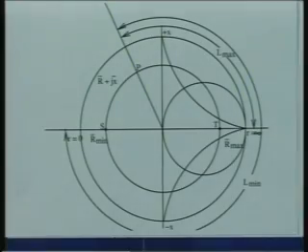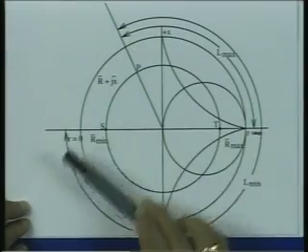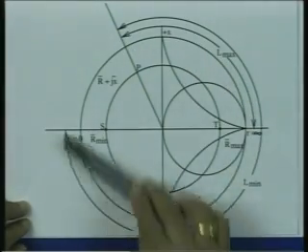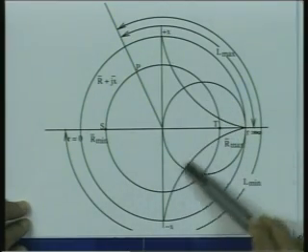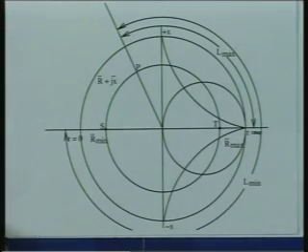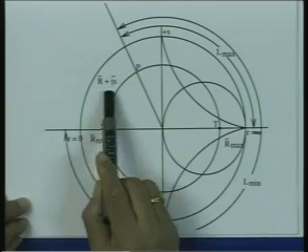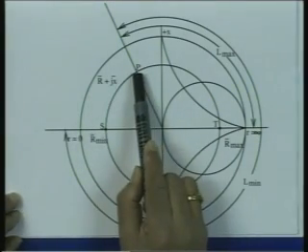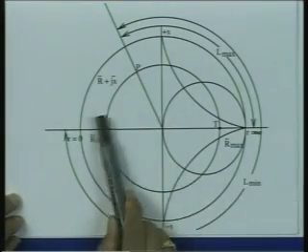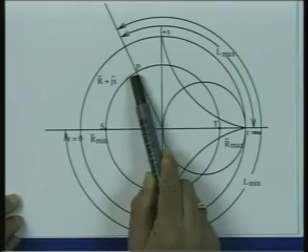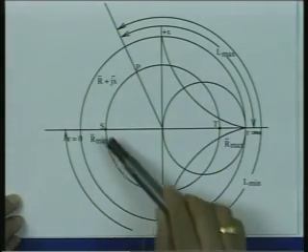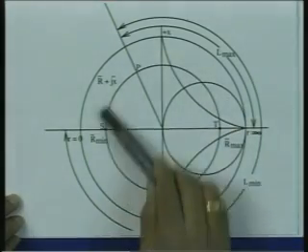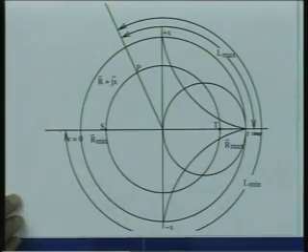So, firstly we take the Smith chart. Here I have drawn the Smith chart with very few circles on it. This is the Smith chart, the outermost circle is the unity circle, and these are the x equal to 1 circles. Let us say my r plus jx in normalized form is denoted by this point P. As we have seen earlier, the first step is to draw a constant VSWR circle through this. So, I draw this circle, which is the constant VSWR circle.